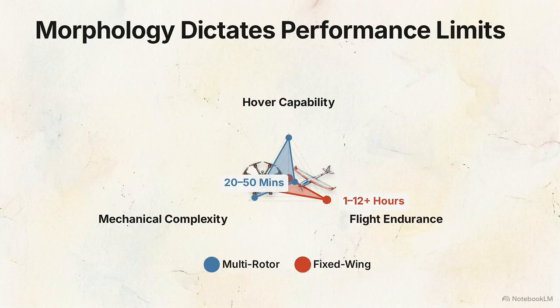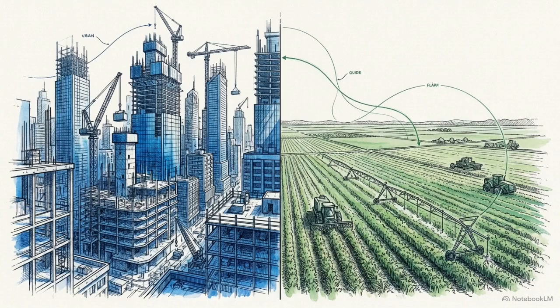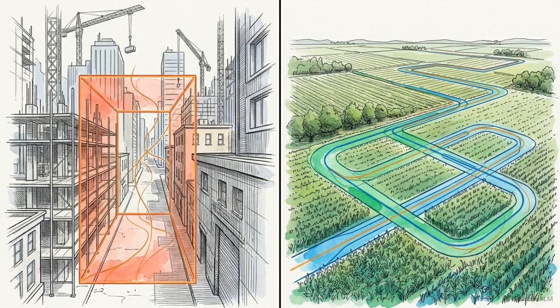This efficiency is traded for stationary control. Fixed-wing platforms drop to 0 on hover capability. They cannot hold a position in midair and require substantial runway space or specialized launching infrastructure to operate. The choice between rotary and aerodynamic lift dictates the operational profile of the aircraft. A mission is optimized either for spatial precision in a confined area or for temporal persistence over a large distance.